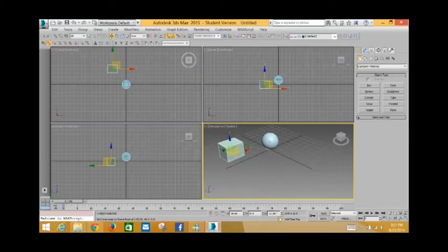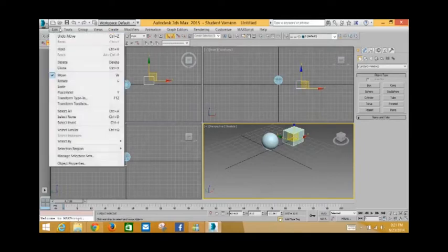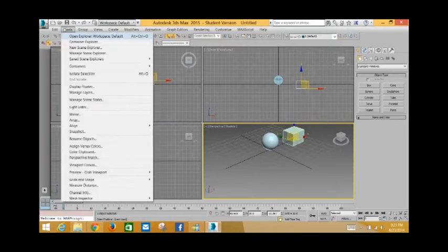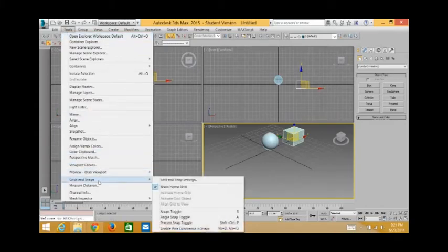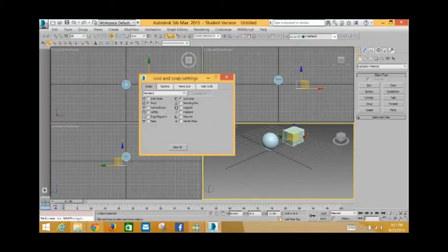You can see that in snapping, when that line is green, it's telling me that it's snapping to a legitimate coordinate. When it's yellow like that, it's telling me that it is not a legitimate snap coordinate based on what I had defined over here. Grids and snaps. This is one way of getting to it. All the definitions of what I'm trying to tell it to snap to.